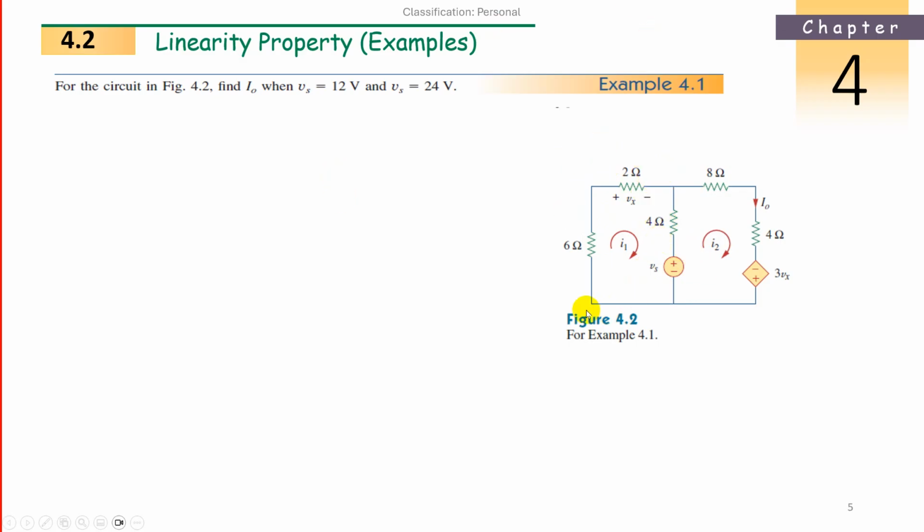Or I will tell another technique today. When you are writing the KVL in the loop, what we can do is just sum up all the resistances and multiply with I1. What are the resistances? 6, 2 and 4. So 6 plus 4 is 10, and 2 more is 12 I1, because the same current is flowing in these three resistances. In the 4 ohm resistor, another current also flows in the opposite direction, that is I2, so put it separately.